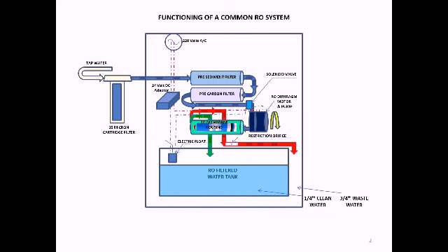From there, one line, the positive line, is directly connected to the solenoid valve, RO diaphragm pump and the electrical float, and the negative line is given through the electrical float fitted in the RO filtered water tank, which goes to the diaphragm motor and pump and solenoid valve. So once the RO filtered water tank is full, it cuts off the power supply to the motor and pump as well as the solenoid valve.